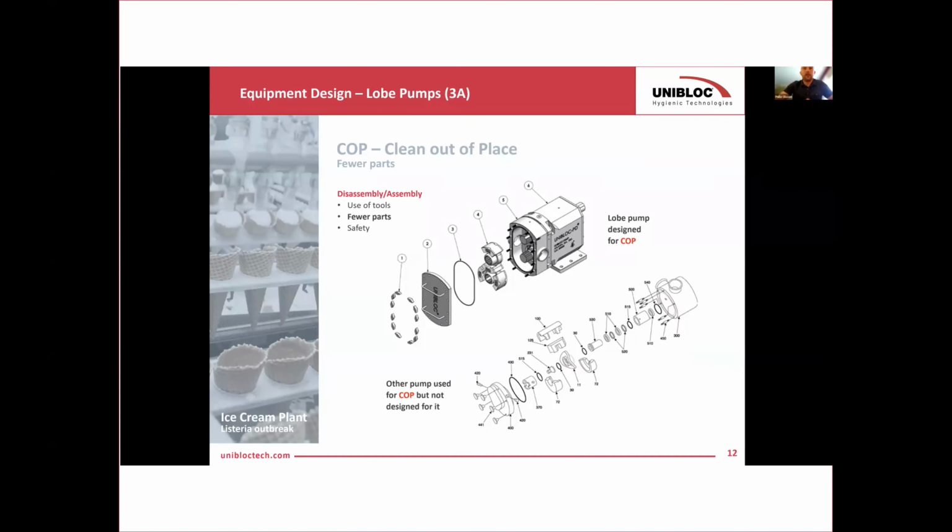So we worked in deep detail with this engineer to find the right solution for him. We tweaked the design a little bit, but eventually we found a good solution for him with a pump that was perfect for COP, with a seal that was easy to change out and to verify is being cleaned properly between each batch. So today they have been in operation for about four years, and so far so good.